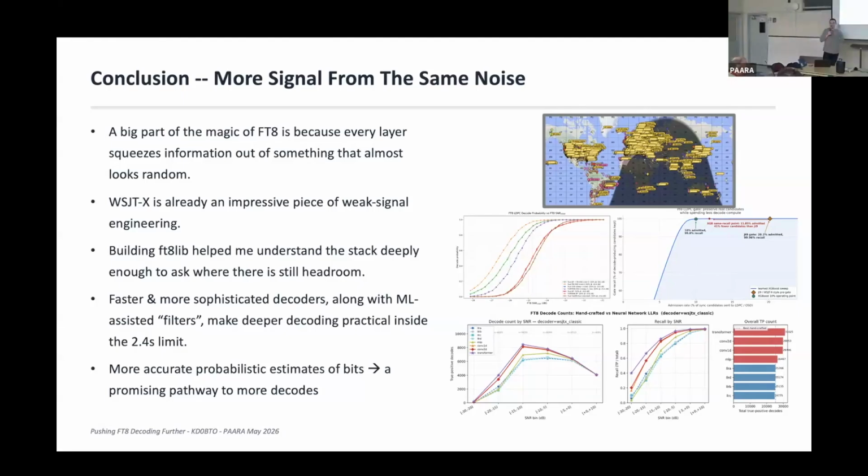Unless maybe there was some element of the phase space, but because all bits are zeros and ones in there. The thing that I think is really interesting is making it more robust to slight frequency and time offsets. Like that synchronization part, it gets close, within 20 milliseconds. But I kind of told you, if you get too far away from that, it starts to die. What data generation would be, the waveforms that you have, you artificially insert little shifts in the frequency and time in it, and you make maybe 6 copies where you're randomly shuffling it around and then train it. I think that's absolutely the way to do it before releasing this. So that's already in my backlog, but I haven't actually done that yet.